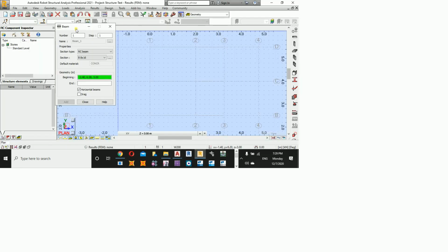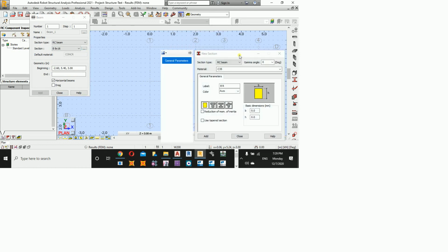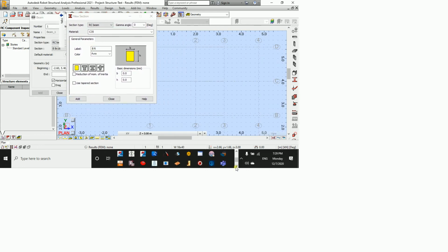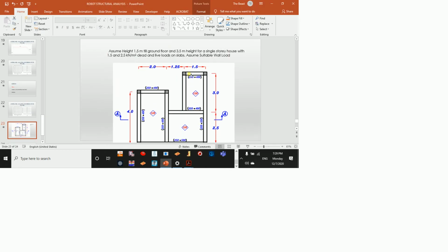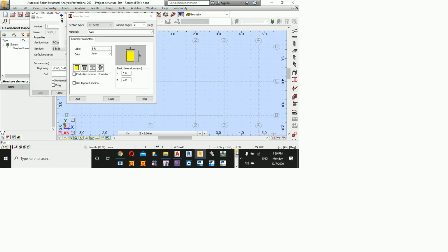Okay, I'll first click on the three dots here. Can you see the three dots? Now the grade of concrete, if we see our problem, it didn't say, so let us use C35. Normally the minimum is 25, but we don't use 25, we use 30 and 35. So let us use 35, but once again that depends on the consultancy itself. So we say 215 to 400, right?